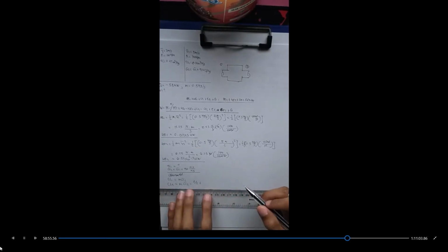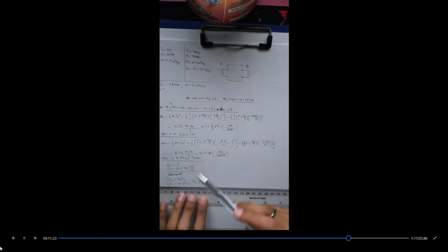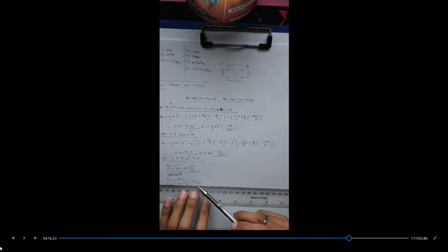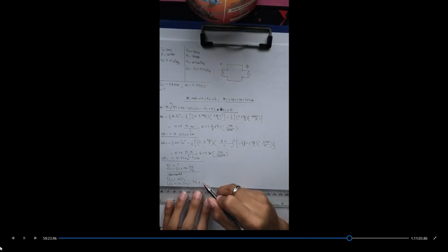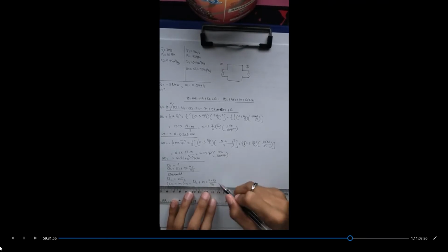I'm just putting U1 here, since if I distribute M to specific internal energy 1, it will become this form, M times specific internal energy 1. So I'm just gonna use this variable, the big U, in order to lessen the space. So I'm just gonna put U1 here, and then plus mass times 90 kilojoules per kilogram. I have a mass of, I'm just gonna show it just like this, times 90 kilojoules per kilogram, just like that. And then I'm gonna simplify it.